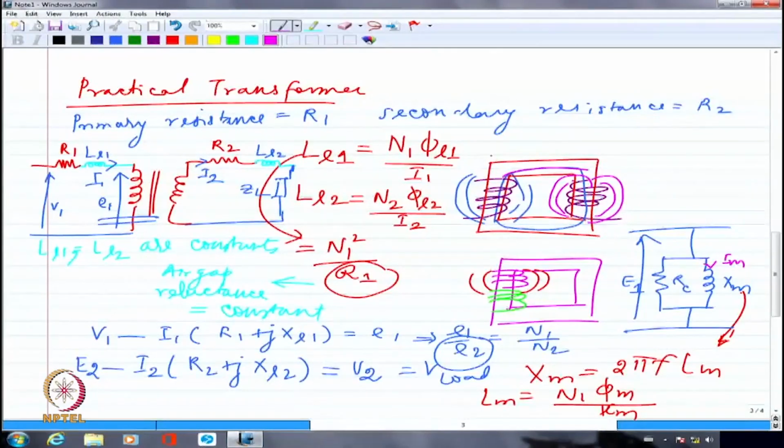Fine? So I want you to refer back to the original discussion of a ferromagnetic core having an equivalent circuit of a resistance in parallel with an inductance. The resistance is representing the core losses. The inductance is representing the current carried to establish a flux.